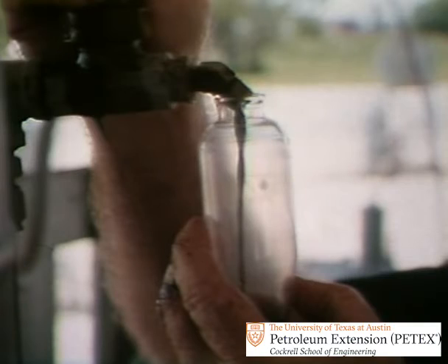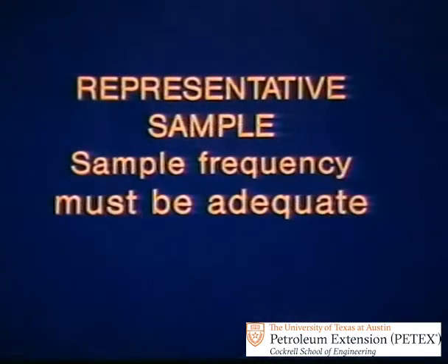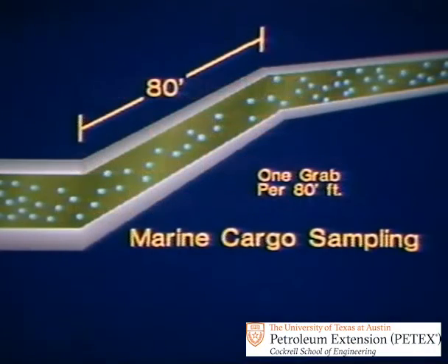So, samples can be grabbed and tested to determine the quality and properties of oil or product in a pipeline. But the samples must be representative. They must be an accurate representation of the oil or product flowing in the pipeline. To get a representative sample, the sample frequency must be adequate. For instance, in marine cargo sampling, where a lot of S&W is concentrated at the beginning of a discharge, typically 1 grab is taken per 80 lineal feet of pipeline volume.